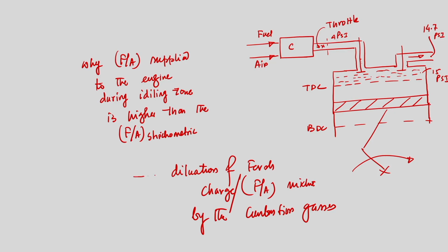Now, although we are not supplying any load from the engine, even to keep the engine in starting condition we need to supply more fuel, I can say a fuel-air ratio which is higher than the stoichiometric fuel-air ratio. We cannot prevent dilution of the fresh charge by the combustion gases.